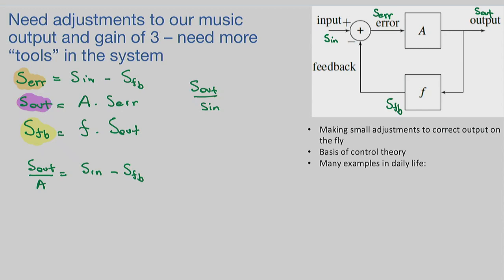So that's also a good equation to substitute here, because now I can say that signal out times 1 over A, which is what we had there, plus F coming from the signal feedback substitution, is equal to signal in.